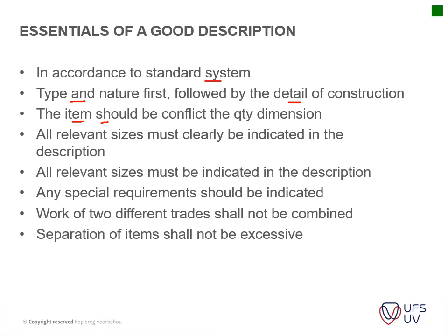It's going to be in conflict with the actual quantity in your description. So for instance, you describe that you've got 3 of these doors and your quantity is not multiplied correctly, then it will cause a claim from the contractor. So usually your doors are measured in number, given you give the size, you give the quality, and you describe what type of connection it will have.